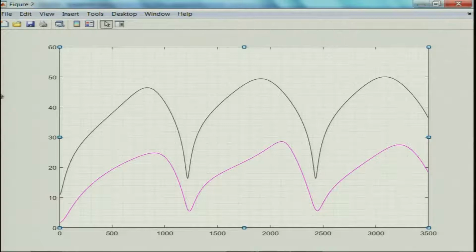I mean one thing is for sure, that we need to use the more modern expressions, because they have been obtained by much more accurate mathematical models, and they have been corroborated quite well experimentally. So I would say that I would trust the predictions based on modern expressions for perforate impedance more, at least for cross flow configurations when mean flow is present.